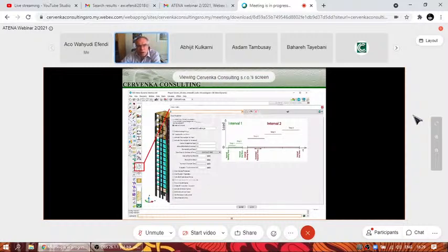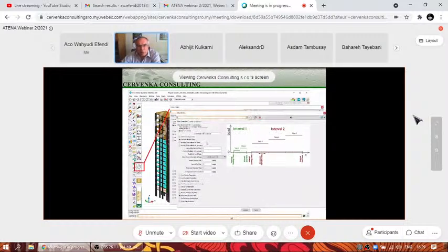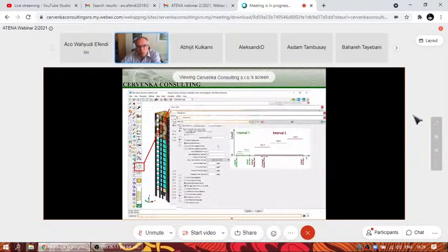So a typical loading scenario is that we first apply boundary conditions and self-weight of our structure. Then in the next interval, we add maybe some additional dead load for the structure. Then we apply live loads for the structure. We always have to define appropriate time intervals. So this, of course, should be with some longer time, because we want to ensure that we don't have any dynamic effects from this loading. So as you can see here, we are applying all these loads over several seconds.